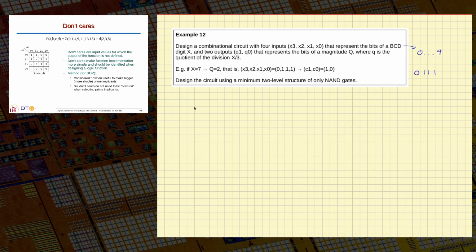So to start, it's good to make it clear what my circuit does by drawing a box and putting all the inputs and outputs of the circuit. In this case, my circuit has two output bits. It's not bad, it's just very common, but it means that we will have to calculate the logic functions for both outputs.